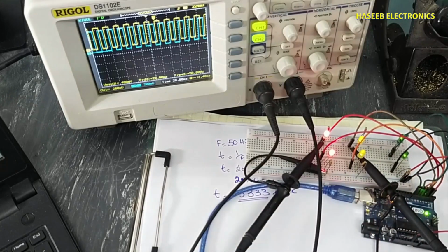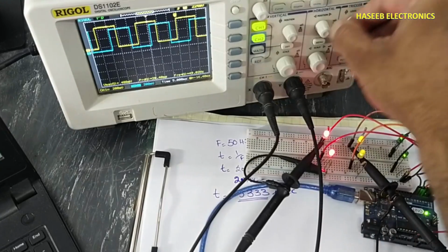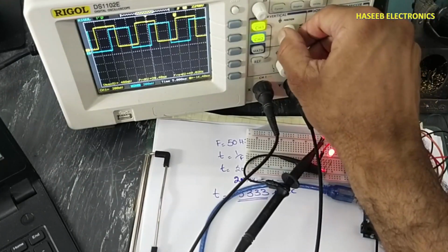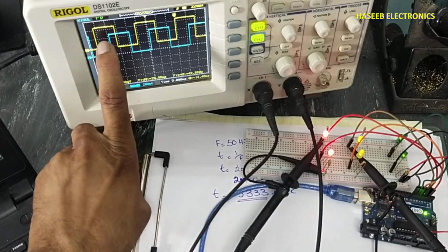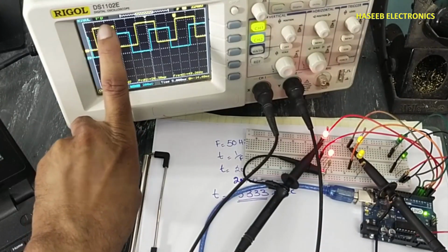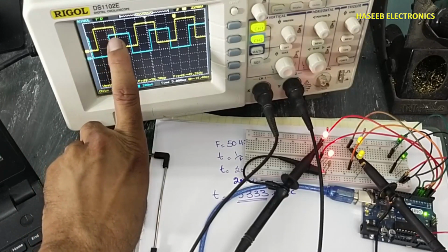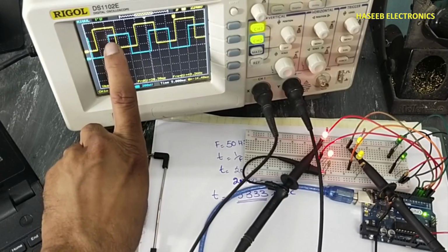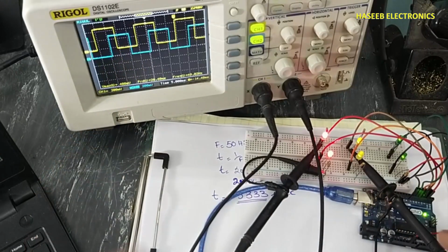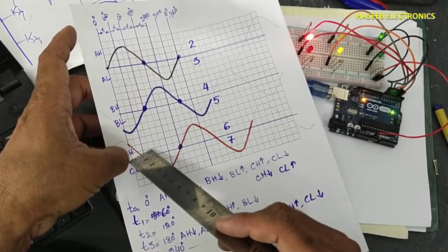Now we will verify phase A and phase B high side signals. Yes, that's perfect. We can see when this channel A is high and it is reaching this portion, that is around 120 degree, that time channel B is starting. A high, B low, C high.